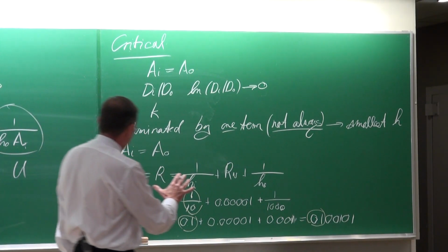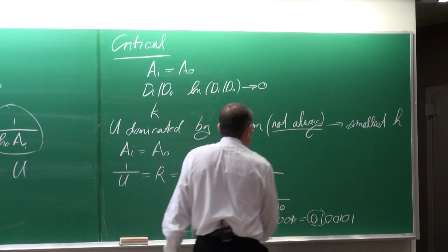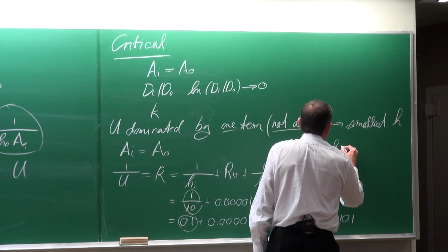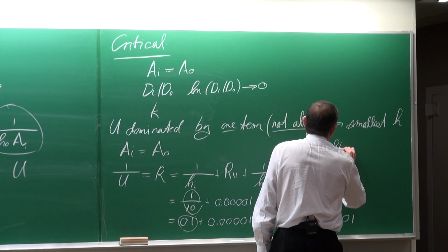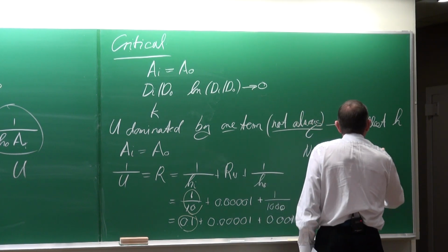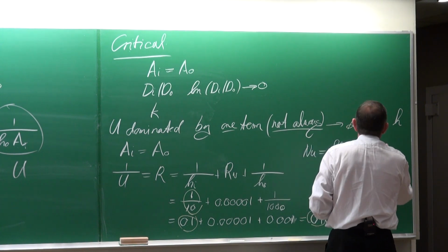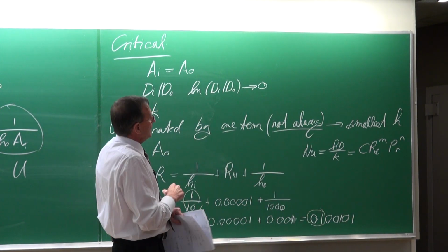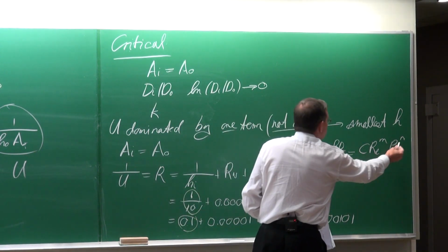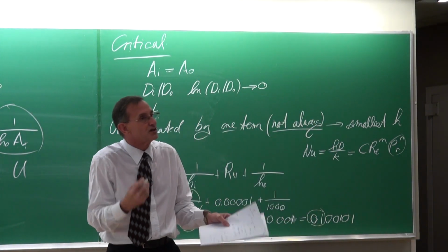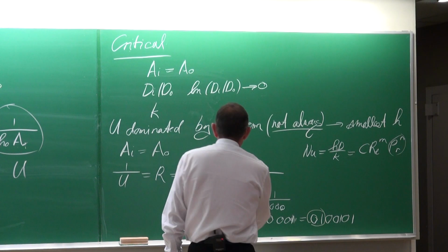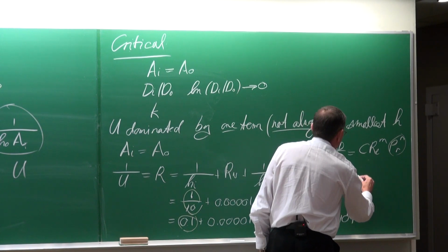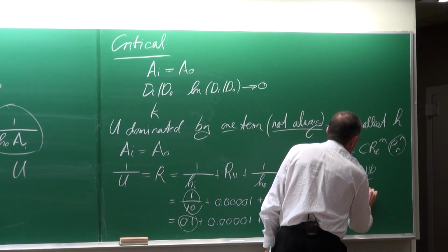Thus, if you've got a problem like this, then you need to see that that heat transfer coefficient is a function of the Nusselt number, hD divided by k, and that can always be written as a constant multiplied by the Reynolds number to the m and the Prandtl number to the n. Now usually if the two fluids are fixed, then you cannot do anything about the Prandtl number because it's a fluid characteristic. So the only way that you can increase the heat transfer coefficient is the Reynolds number, which is rho V d divided by the viscosity.